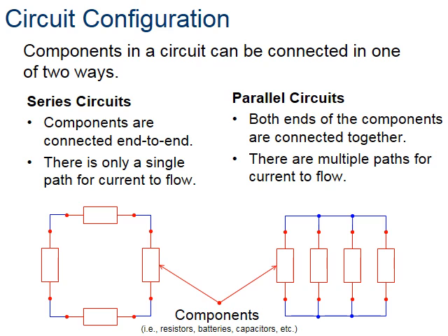First, let's talk about what is a series circuit and what is a parallel circuit. And here you see some basic diagrams down below. A series circuit on the left basically just has one path for electricity to flow. And you see the red rectangles? Those red rectangles can be anything. Those can be batteries, those can be light bulbs, a lot of different things. It can be inductors or capacitors or all kinds of other things. So those just are generic components. So in a series circuit, there's one path. So if I cut that path, current does not flow.